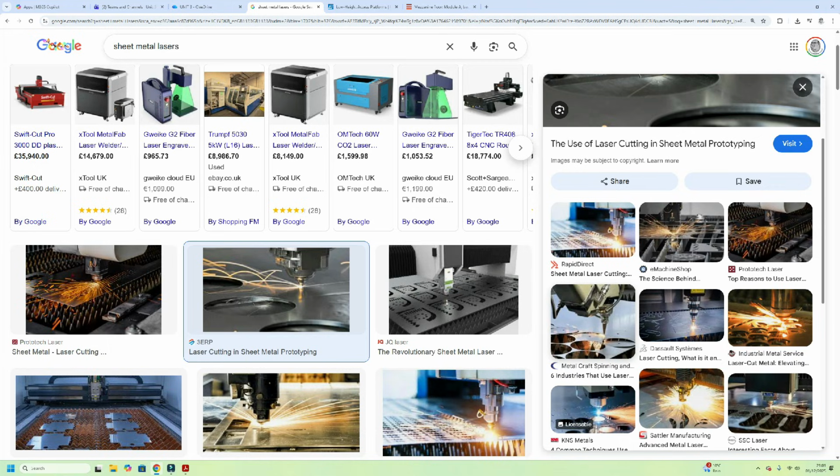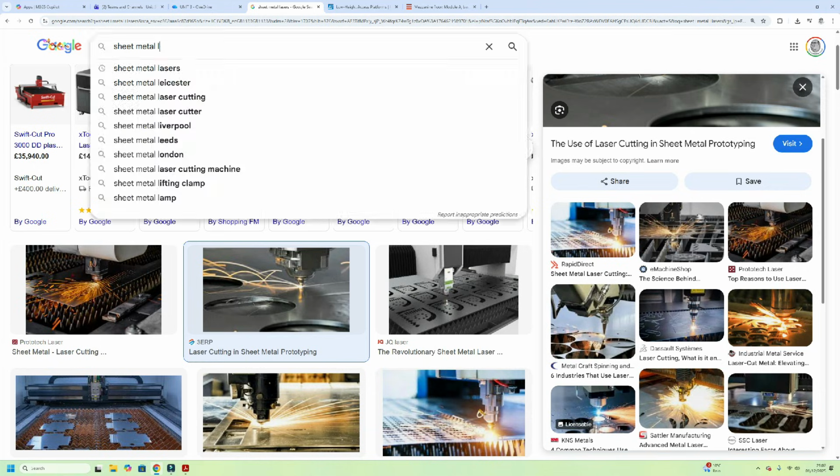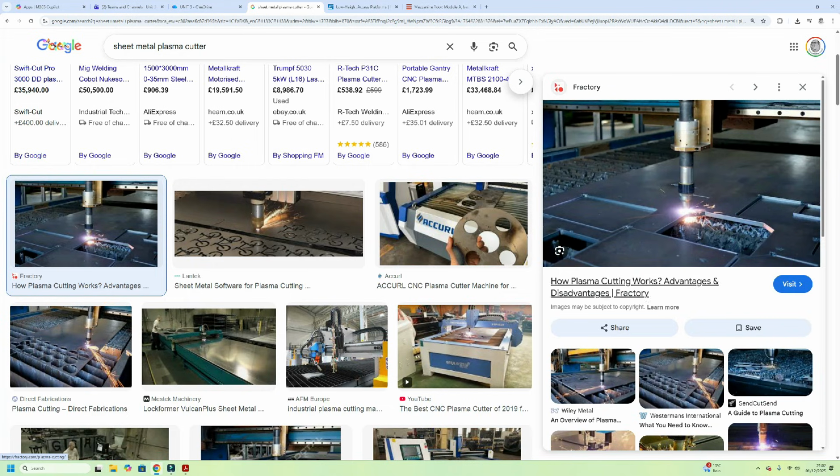Okay, so when you use your Inventor, SolidWorks, Fusion, whatever CAD package you have, you can save that image and send that file as a DXF to your laser cutter, and they will use their software to lay as many parts as they can on that sheet of metal. That's called nesting, and they cut as many as they can out of those parts. If you want 1,000 of those pieces, the software will show you how many parts can be laid on the sheet metal. Now, if you look at plasma cutter, the edge is not as clean as the laser.